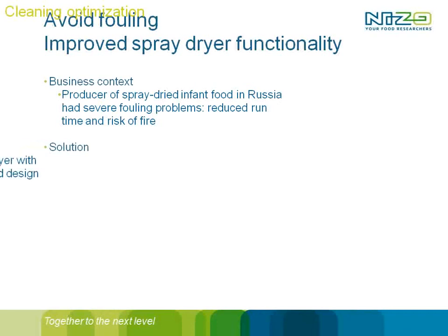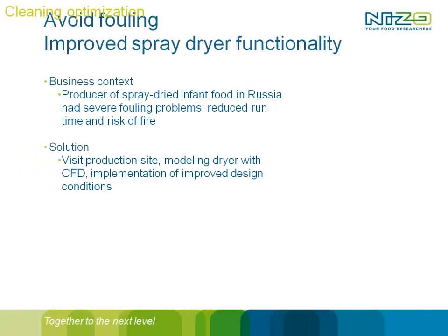We had a producer of spray-dried infant food in Russia, and they had severe fouling problems. And the fouling inside a spray dryer is actually a high risk. I mean, in a spray dryer you have hot air, you have a powder, and if you have a small spark, you have the ideal ingredient for a bomb. It can explode, and that's something you don't want. So try to avoid the spark, since the hot air and the powder are necessary for your spray drying process.